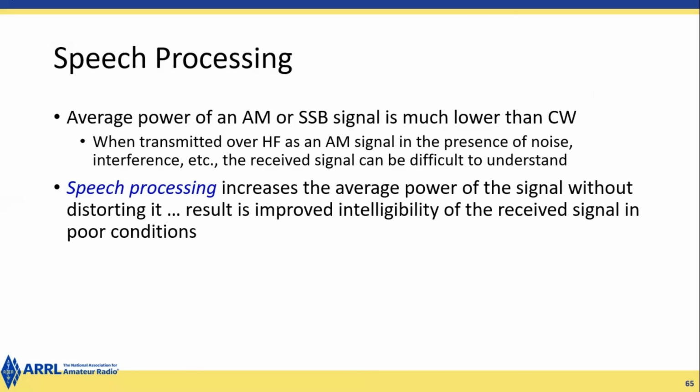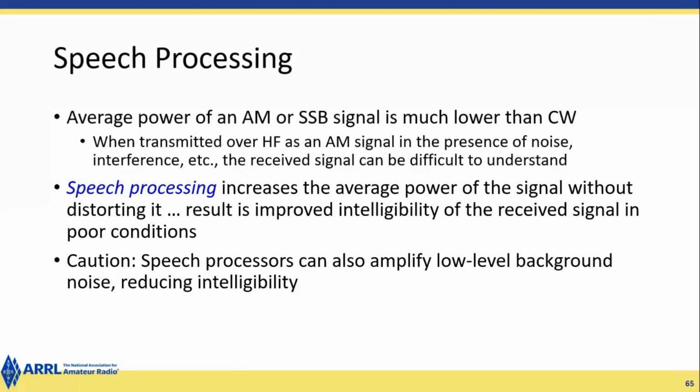So a lot of the modern radios have speech processing. You can turn it on or off, and it works pretty good, but you have to make sure you've got it all set up right and adjusted correctly. Speech processors can also amplify low-level background noise, reducing intelligibility. So be careful of that.